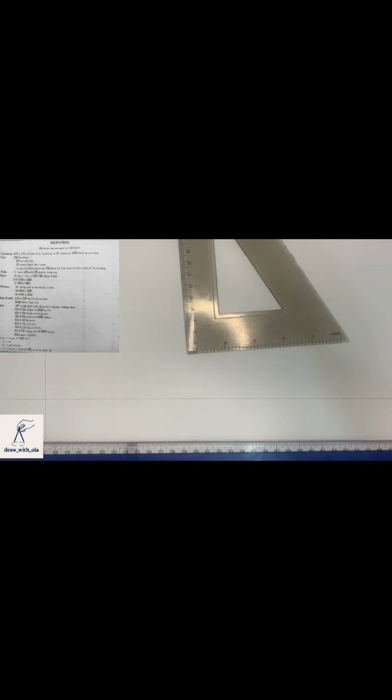Next we'll start picking the walls, the windows, and wherever the section line cuts through. Remember, we're drawing in scale 1:50. First we start with the wall thickness, which is 225, right here. Next we move over to the length of the WC and the shower, which is 2,800. This is 2,800 right here.